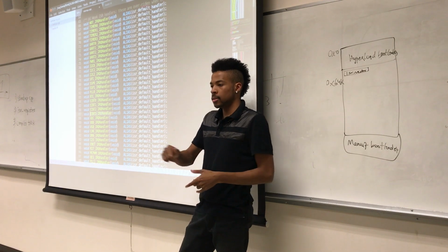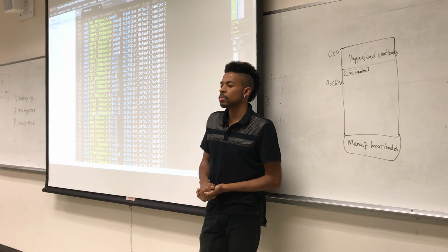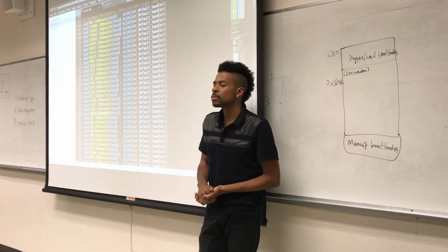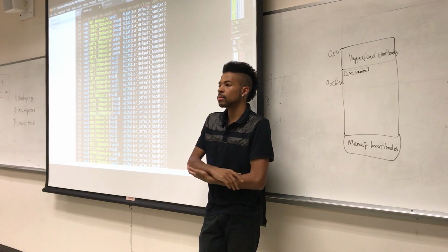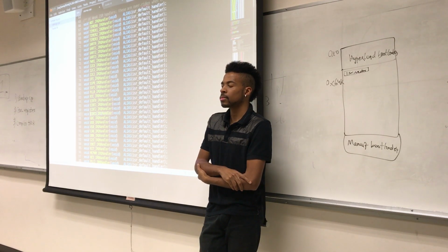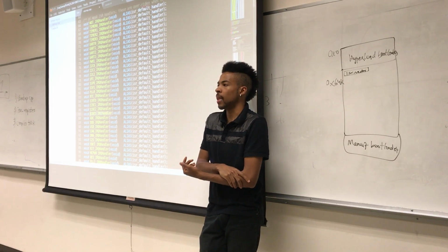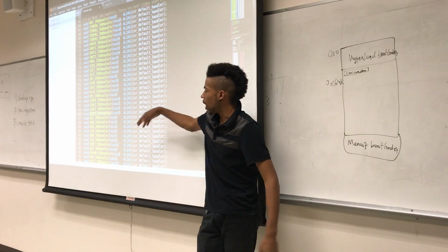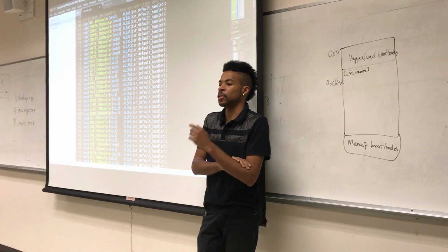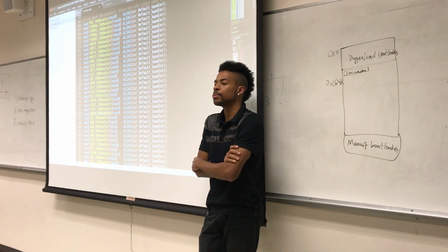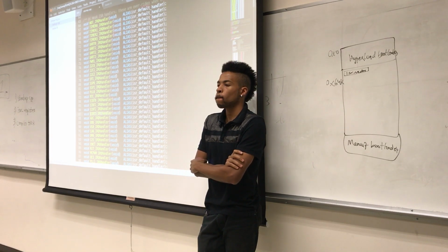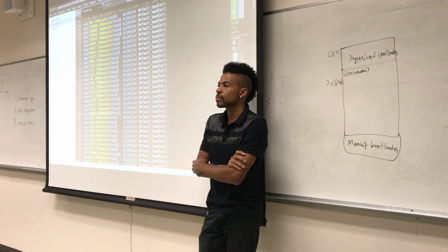So the handler should be the one that finds that function, right? Yes. Okay. And then the pointer to that function should be going to where that callback function is actually defined. Yeah, you have to store that function pointer somewhere, and then this guy will execute that function if it sees that particular bit has been set or that particular interrupt has occurred. So that would be something that we would maybe put in our external interrupt 3 class. Yes. And then this handler should be external to that class, right?